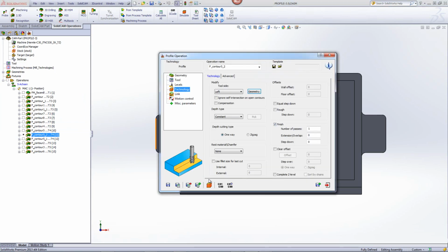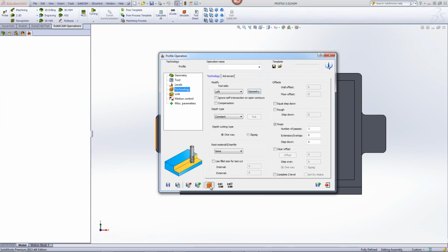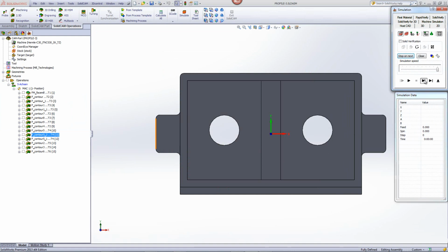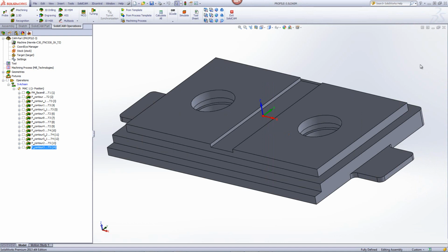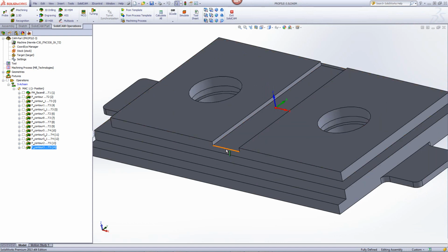Now if I take a look at my geometry, you'll see that the tool in this particular case will now go on one end, finishing off, and then going back on the other end as shown over here. Now the last option I'd like to show you in modify geometry is using the extension but in the negative value. What I'd like to do is as follows. I'd like to actually put a chamfer on this edge over here and on this edge over here. Now if I use this entire chain, the tool will obviously eat away at this corner. So let's see how I deal with this.